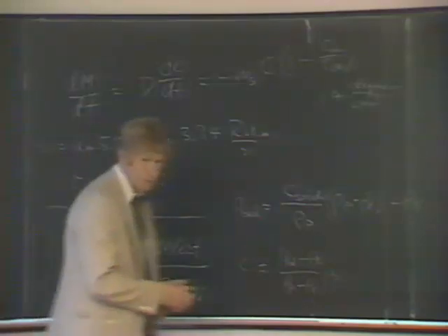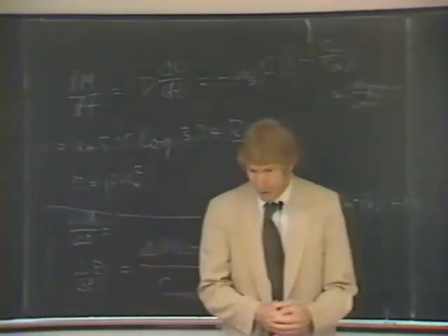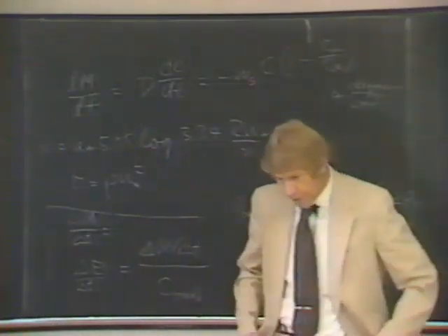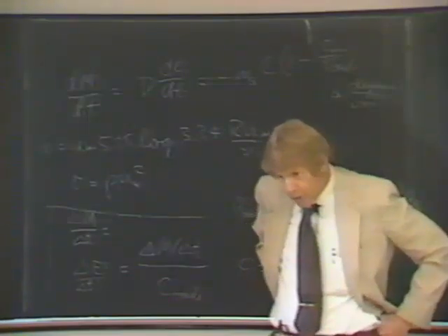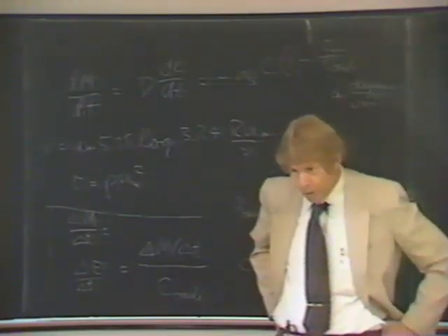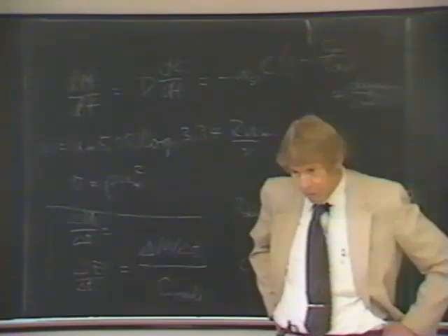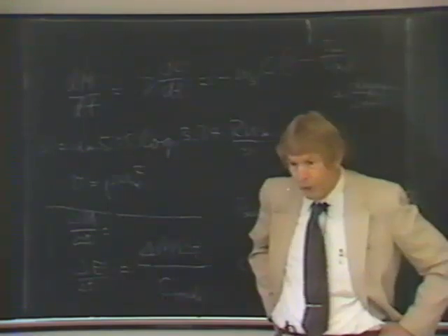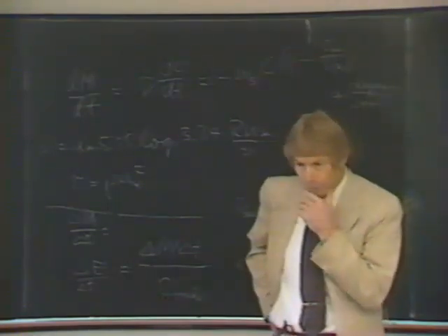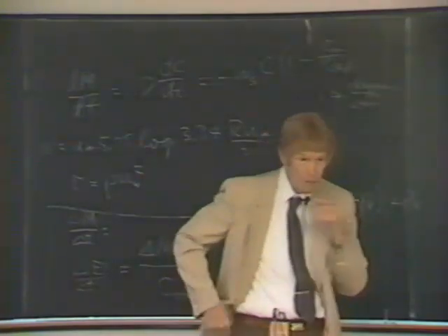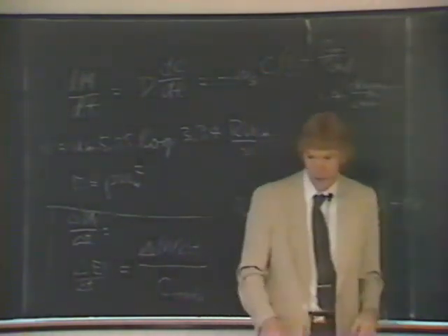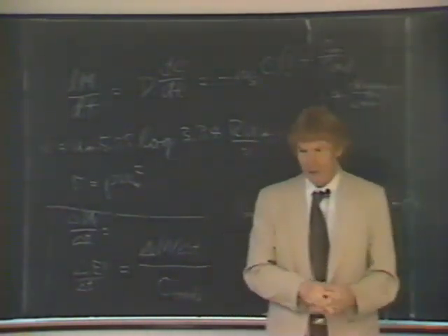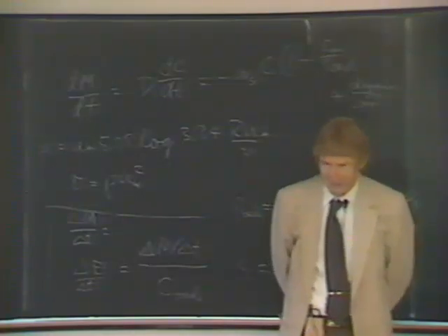On the previous problem, I made the assumption that R was equal to D in my calculation, but based on your last lecture, it seems like maybe an assumption of a rectangular section would be better. I mean, a square cross section. Because last time you said that sloughs were really deep and narrow versus wide and shallow. In sloughs, that's typically the case. They are deep-sided. This was a slough, right? Yeah, so R equal to D was kind of invalid in this case.